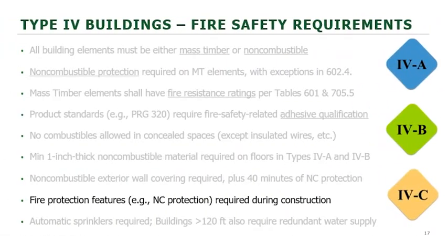There are also requirements for non-combustible protection to be applied during construction and for water supply to be present, and standpipes need to be installed as well. The requirement for non-combustible protection during construction applies to mass timber surfaces that are more than 4 stories below the uppermost floor under construction.